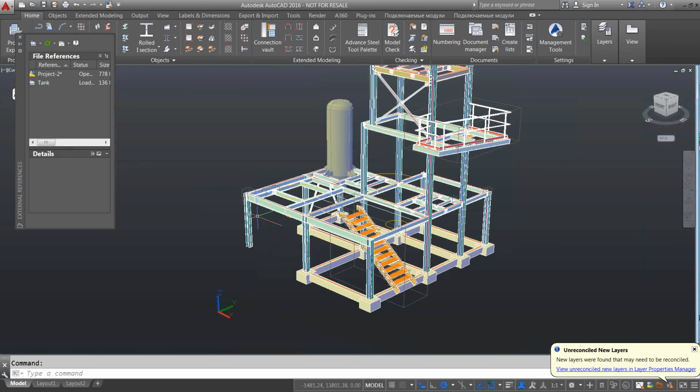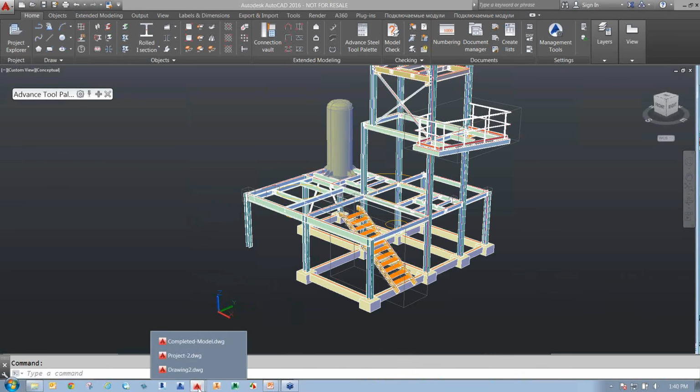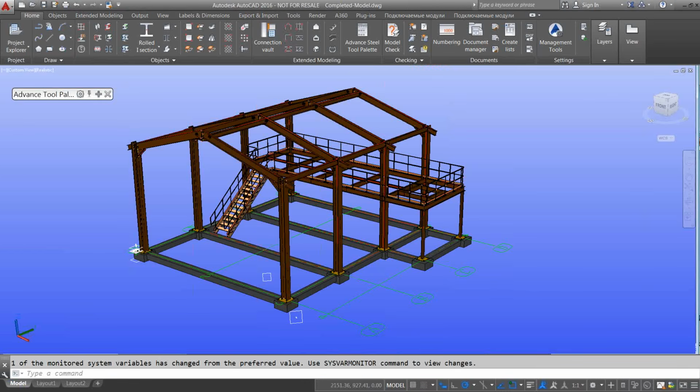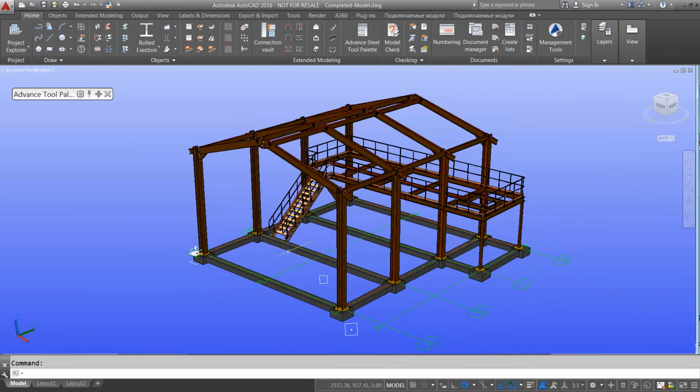As I said, a lot of people use the normal copy paste command. In my case, I prefer xref. The whole idea is that if the model changes, I just need to re-export the file. Now, quickly going back to the third file that I've got open, in which I've created quite a few things. So in this case, stairs, modified, and so on.